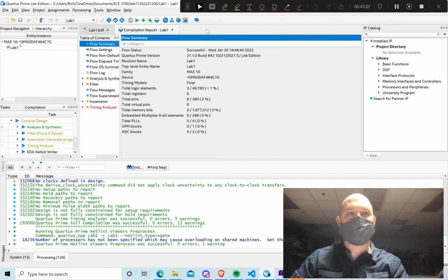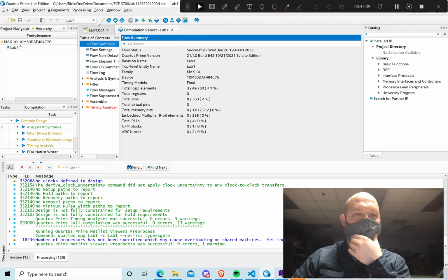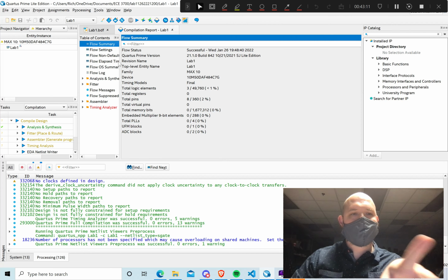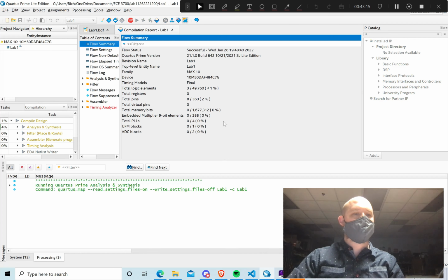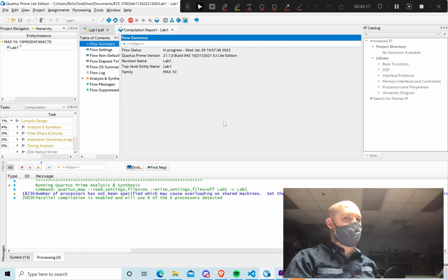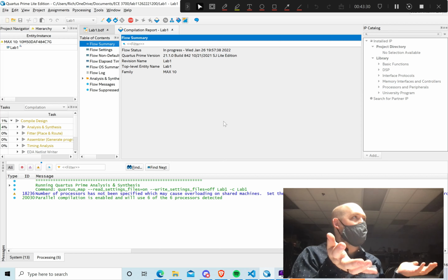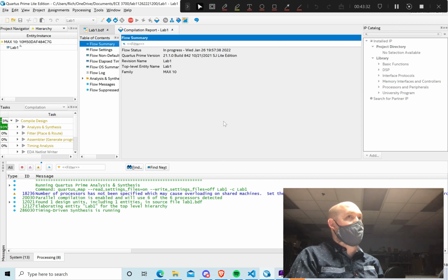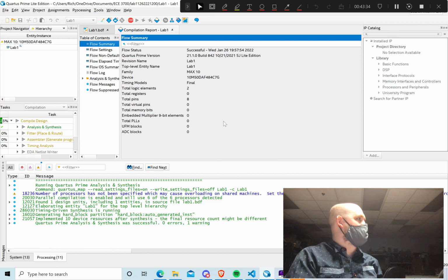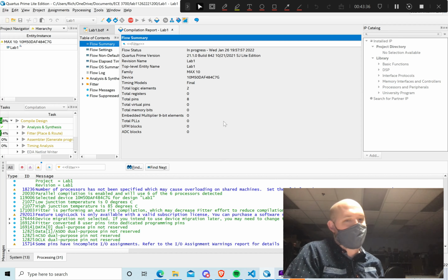Okay? Great. So now that that's been done and I've made my assignments, I have to compile a second time. I have to compile once so that the pin planner knows about my ports, and I have to compile a second time so that my programmer knows about my assignments. It's kind of a silly thing. I don't know why. You would think that they'd be able to figure out the ports without a compilation, but apparently not.